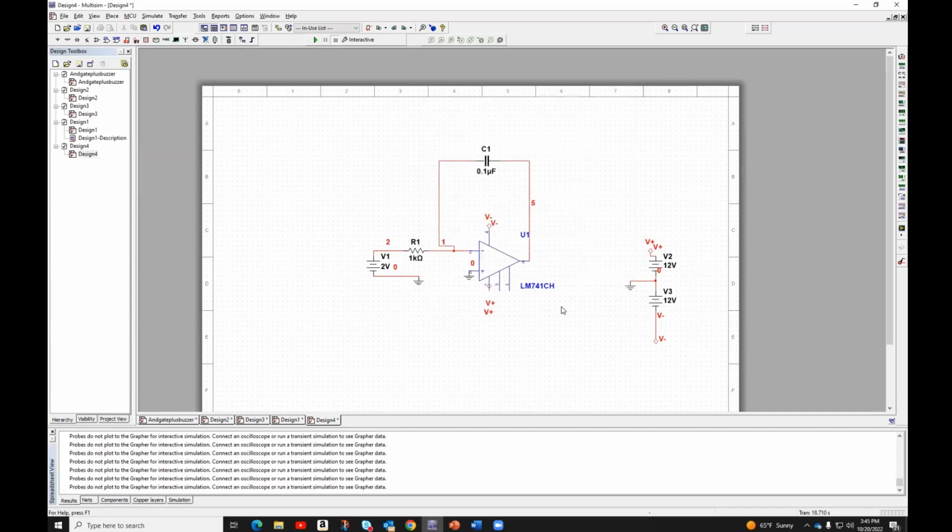All right. So as we said before, what this circuit will do is integrate the input signal. To do that, instead of using a battery, I'm going to use the function generator that we used before, so you remember, and I'm going to hook up my input to the function generator.